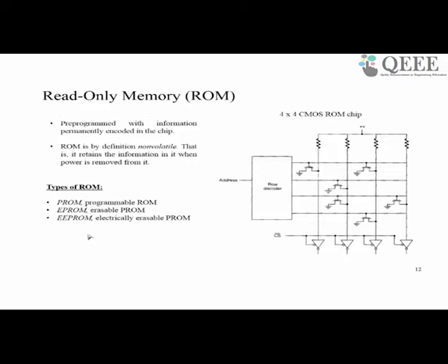Let us assume that it is a memory with 4 locations, each location storing 4 bits. So you have an address port of 2 bits which selects 4 different memory locations, which we can number as 0, 1, 2 and 3, and there are 4 bits stored in these locations. In order to do that, we have to hard code the data that is being stored.